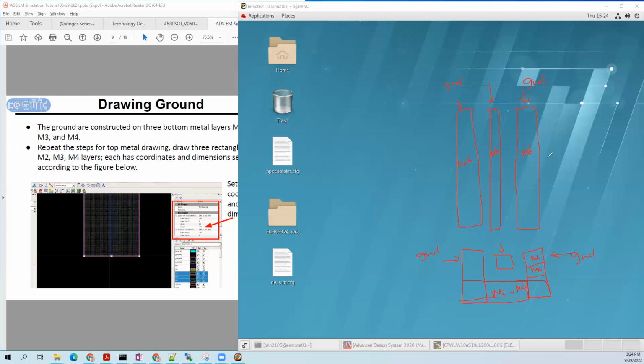The characteristic of the coplanar waveguide is going to depend on the dimensions of the width and the spacings. And then we have to choose which width and which spacing is correct in order to provide a 50 ohm impedance. I see. So is it linear? For example, we do 10 in width instead of 5, and then the spacing is going to be double, which is 10, like 10 width and 10 spacing. But if you do 5 width, then you will do 5 spacing.